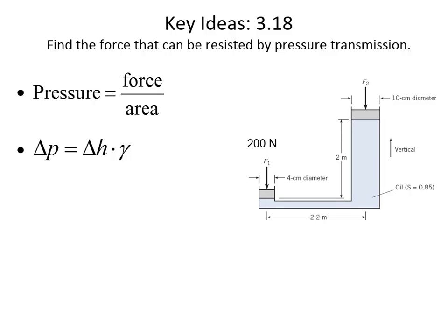I did a culvert analysis recently when someone's culvert failed because the water was rising really high during a storm and it was washing the soil around the culvert. They thought for sure that the fact that the channel gets a little bit narrower 100 meters upstream was the reason why their culvert was failing. And I mean, you don't want to insult somebody who's paying you, but that didn't have anything to do with what was causing the culvert failure.